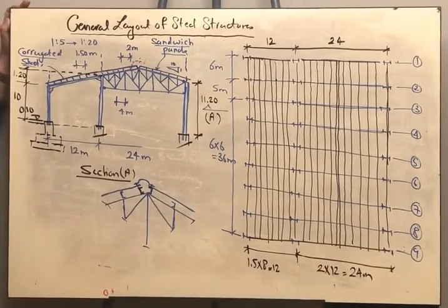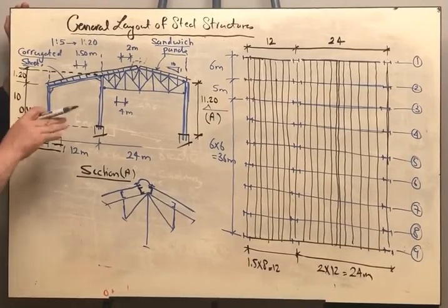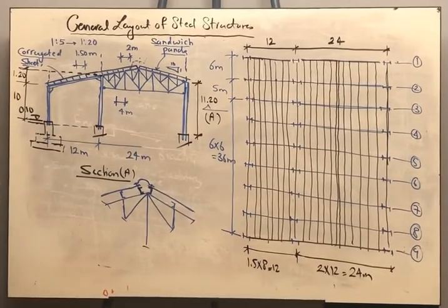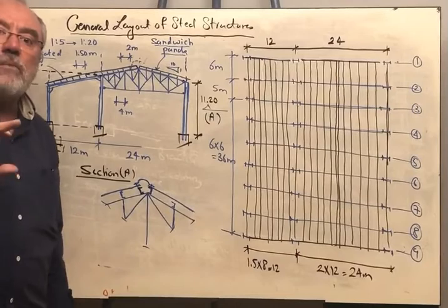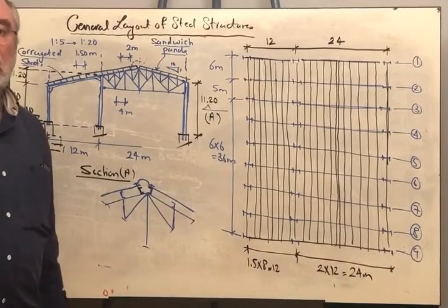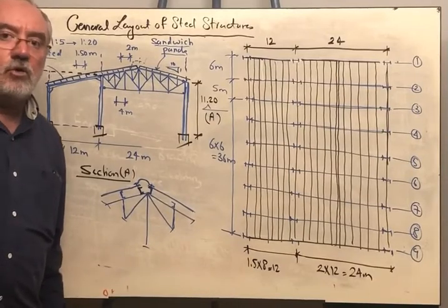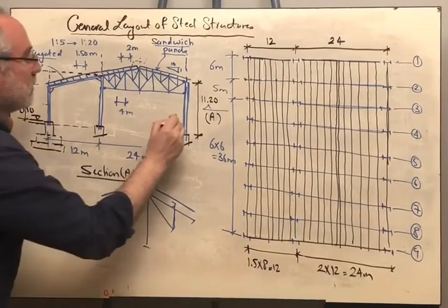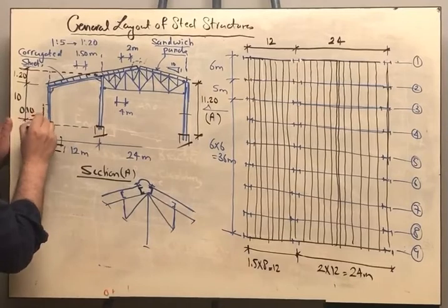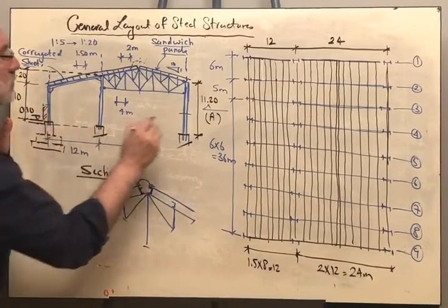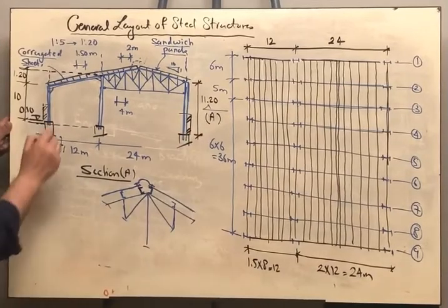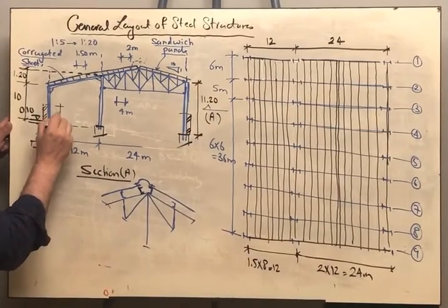Okay? For the side cladding, we have seen that we are using brick wall in the lower part. The height of the brick wall ranges from 1 meter up till 3 meters. And after that, we are covering with corrugated sheet. So we are going to fix here the level, this level, up till 3 meters, we are having brick wall. Okay, so this part is 3 meters.